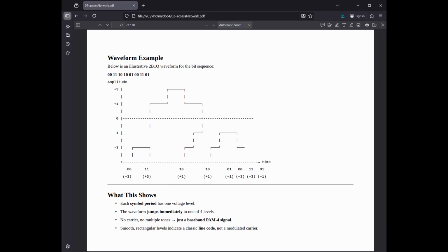2. Presence of a DC component. As mentioned in previous sections, 2B1Q is not DC balanced. Low frequency noise: if a sequence of bits results in a constant voltage, like long strings of zeros, it creates a DC offset. Spectrum waste: this energy at 0 Hz, DC, and very low frequencies cannot carry data through transformers or AC coupled equipment, yet it still generates heat and potential interference. Modern spectrum-friendly codes like 4B3T or DMT ensure the energy at 0 Hz is 0, a DC null.